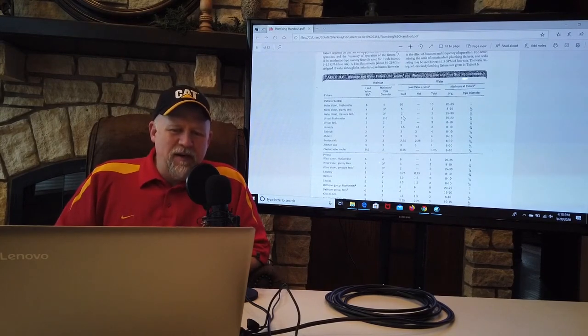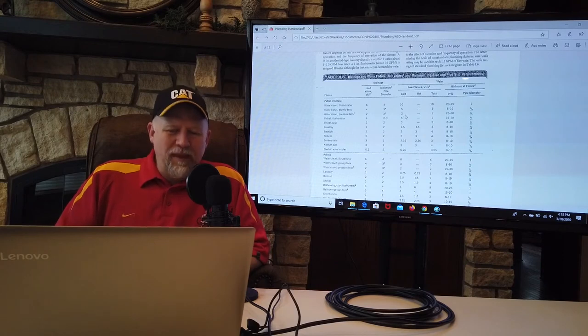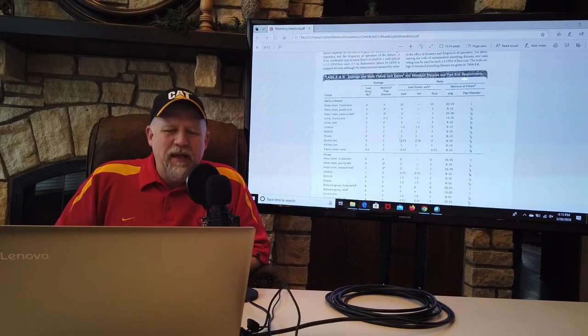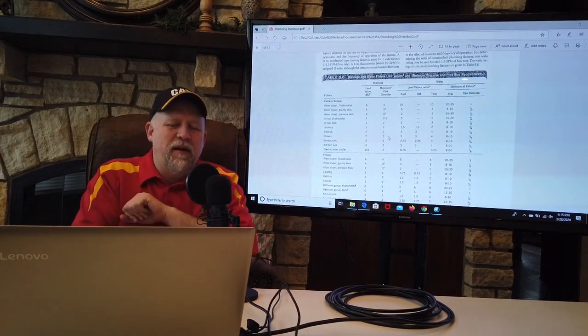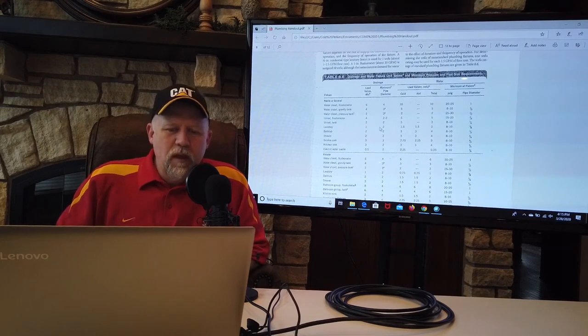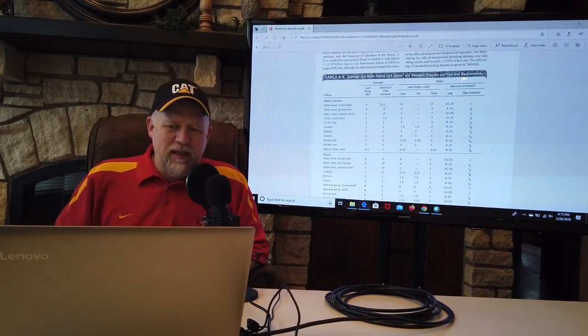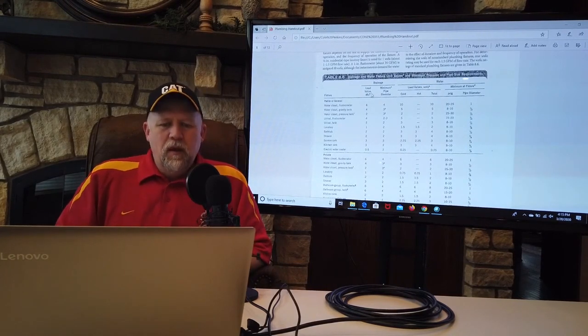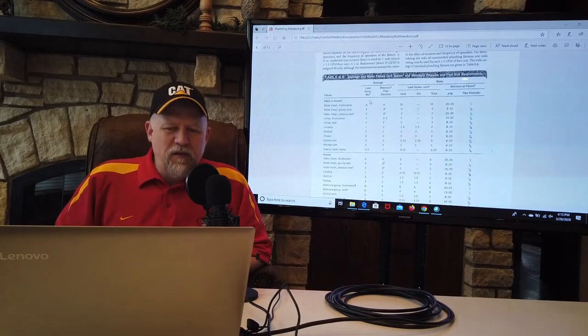They help the designer calculate what the average flow rates are going to be and size the pipe based on a maximum that's going to go through them. So let's take a look at these units. Today we're just going to be talking about drainage fixture units. All right, so let's take a look at drainage fixture units.